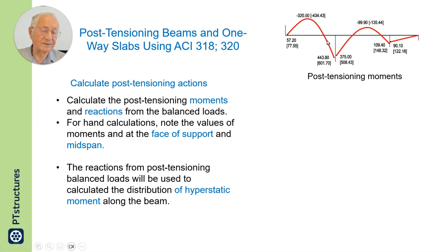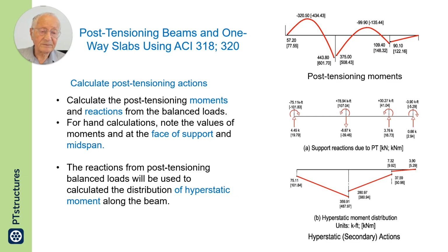At the top right, I have the moment of post-tensioning forces, and in the middle, the reactions from post-tensioning at the supports. These reactions are the hyperstatic actions. I need the hyperstatic actions when I go into safety check. And from hyperstatic actions, I form a bending moment diagram.